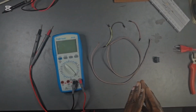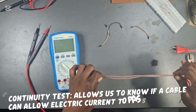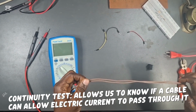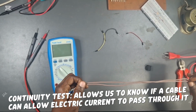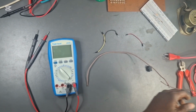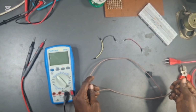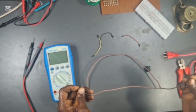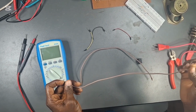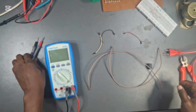Let us proceed to perform continuity test. Now, continuity allows us to know whether a cable is able to allow current to flow through it or not. If a cable passes a continuity test, that means that current is able to flow through from one end to the other end. And if a cable fails a continuity test, it means that current won't be able to flow through from one end to the other. Now, shall we proceed with the testing?